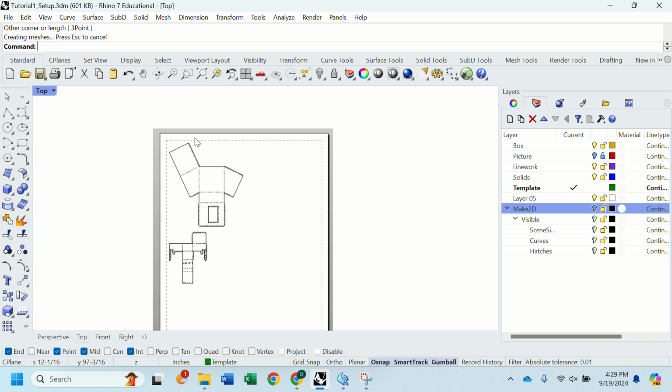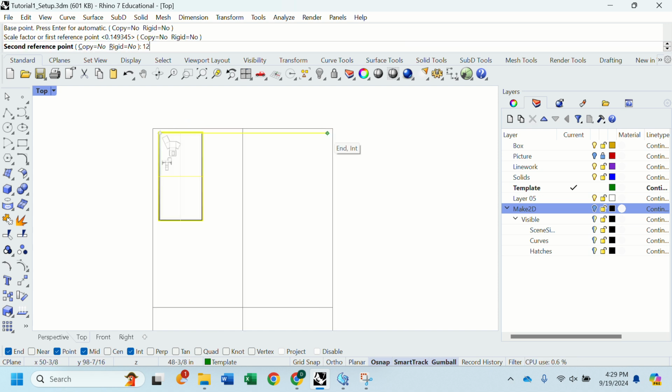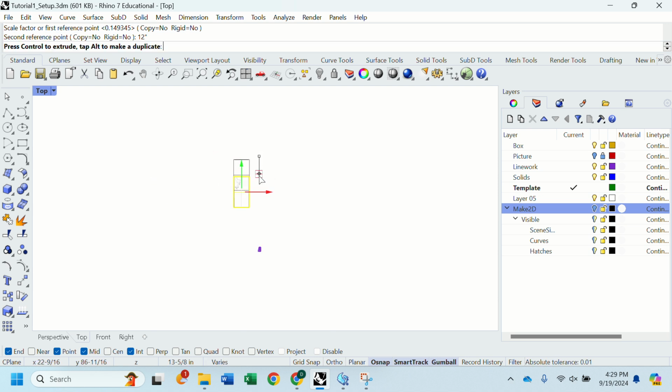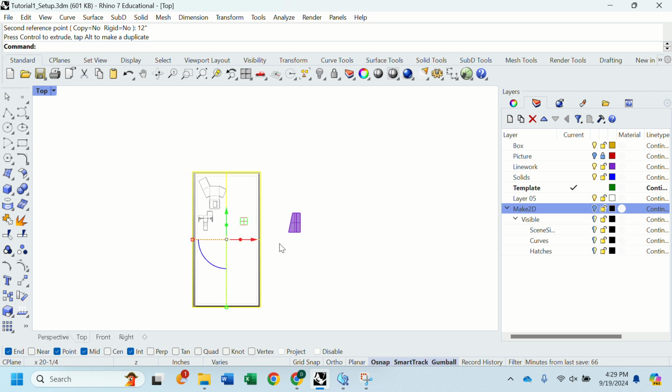Now remember we talked about making sure that we screenshotted the whole page. That's because we really want to scale the whole template up accordingly so that it's the same scale, right? Otherwise we would have no idea. So if we use this whole page here, I can run that scale command and make this 12 inches. Now, let's bring that back down to where we've been working.